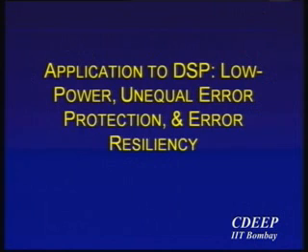Leakage does play a role. If you scale your supply voltage down, it's going to have lower leakage, right? In general, you're going to have a lower DIBL, and due to lower DIBL, you're going to have lower leakage, if you don't consider other forms of leakage. And in fact, even other forms of leakage would reduce. We didn't directly look at the leakage reduction. It was really more from the dynamic power point of view, but the leakage power is going to reduce. The measured results would include the leakage power consumption too, but leakage would improve.